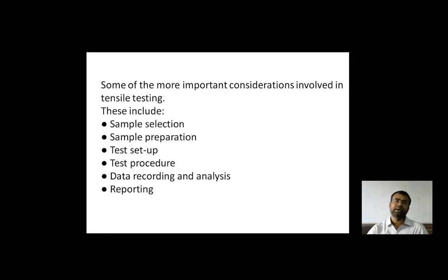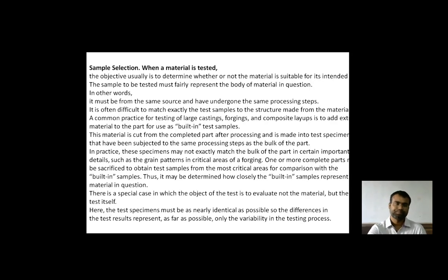Now we have reached our concern: the tensile test, and how important it is to consider the involvement of tensile testing. These include sample selection, sample preparation, test setup, test procedure, data recording, analyzing, and reporting. All these things must be taken care of when we examine the test specimen for the tensile test or to examine the ductility.